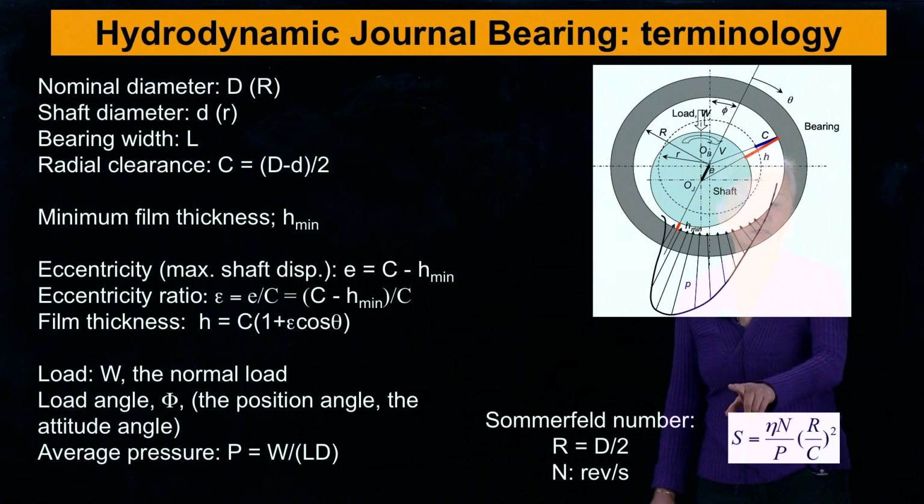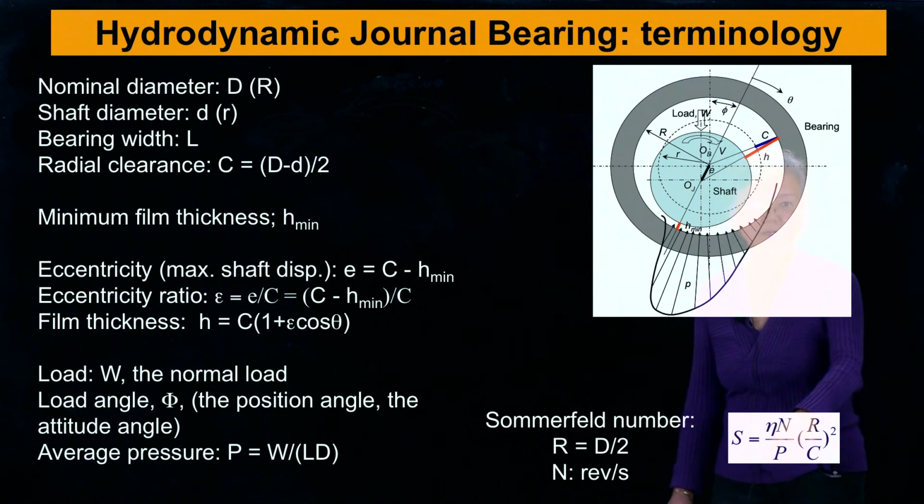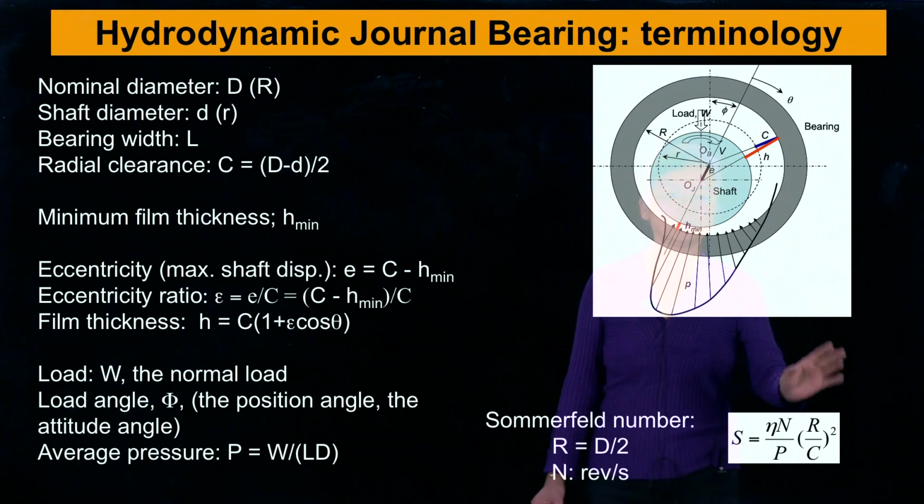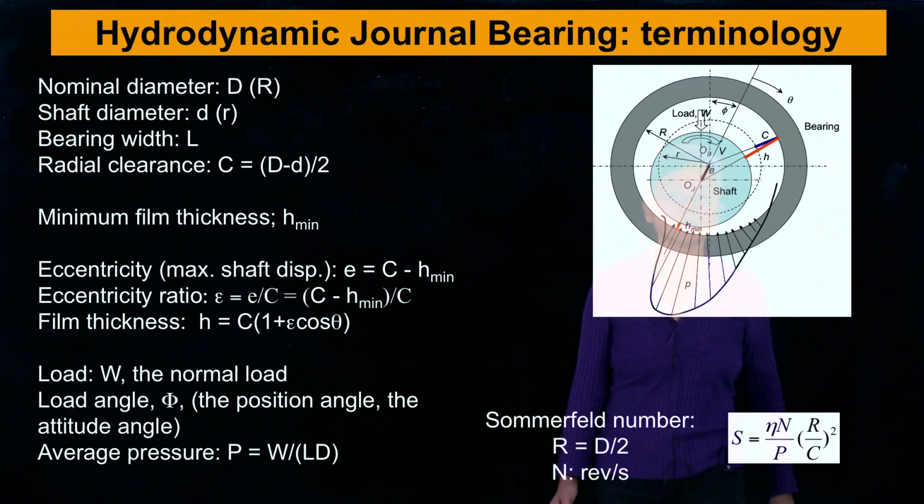The Sommerfeld number S gives us the load capacity. Actually, the Sommerfeld number is the reverse of load capacity because the average pressure here contains the load. But this is a very important parameter. We're going to use this in class. Thank you.